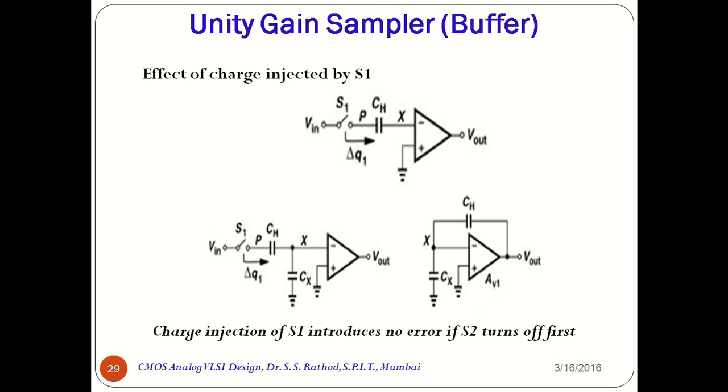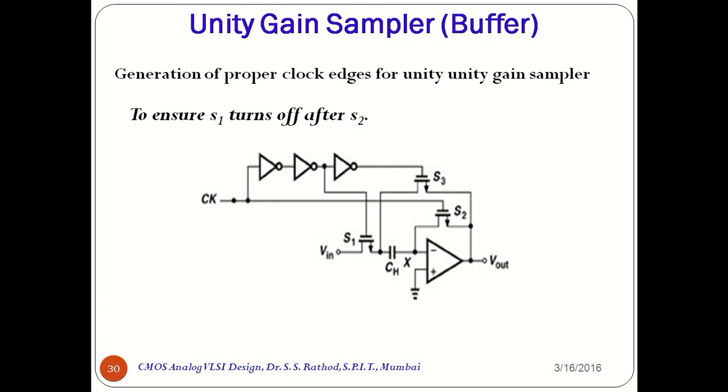So what this figure shows is the effect of charge injected by S1. Charge injection of S1 introduces primarily no error. However, the condition is that S2 should turn off first. Thus, it is very important to synchronize these switches. So S2 should turn off first. Therefore, this clock will ensure that S2 turns off first.